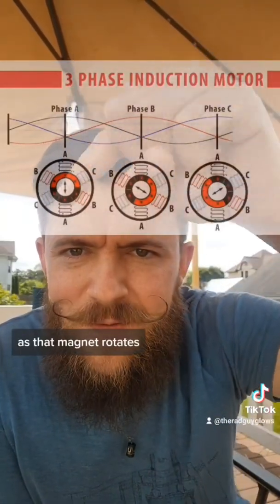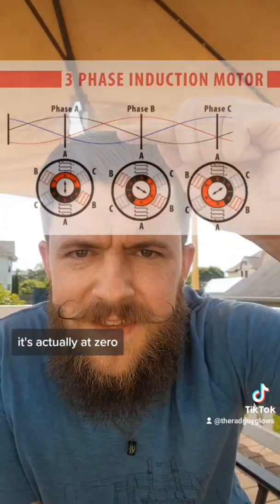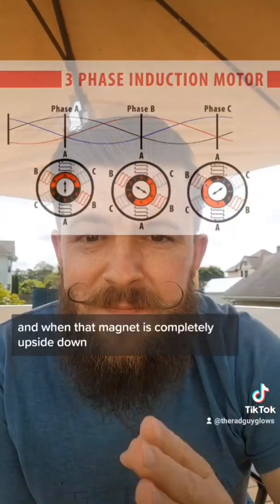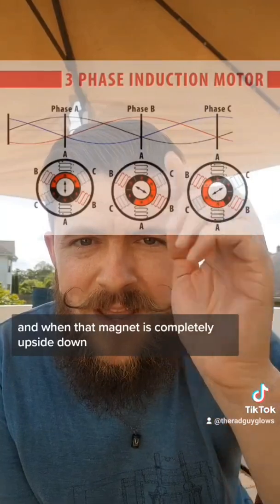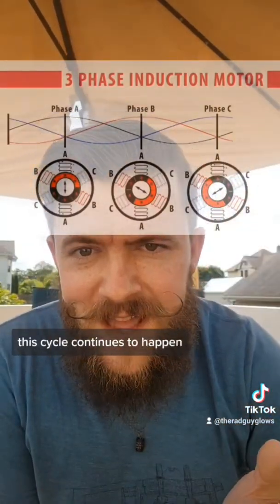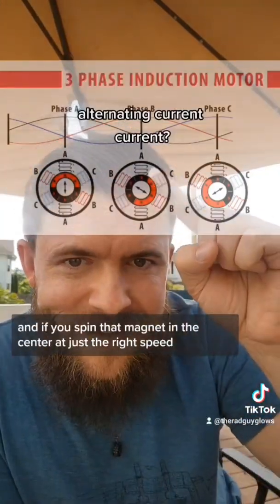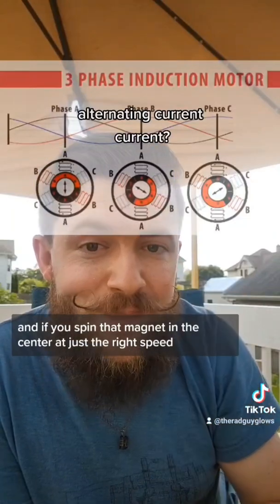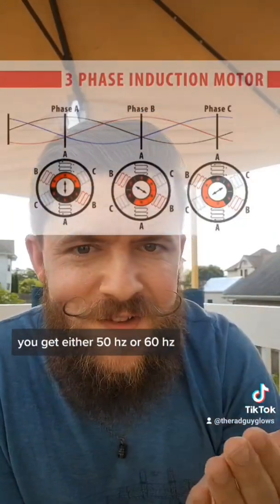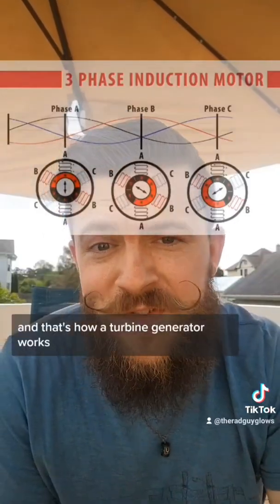As that magnet rotates, the voltage will go down. When that magnet is completely perpendicular, it's actually at 0. And when that magnet is completely upside down, that's when the voltage is at its minimum. This cycle continues to happen, and that's why you have AC current. And if you spin that magnet in the center at just the right speed, you get either 50 Hertz or 60 Hertz, depending on what part of the world you're in. And that's how a turbine generator works.